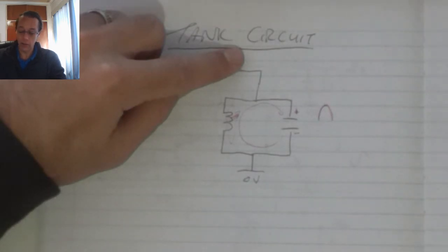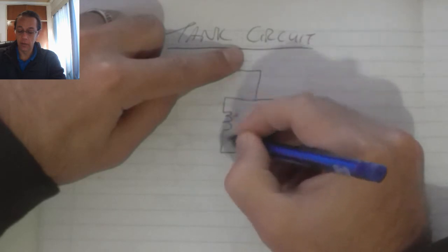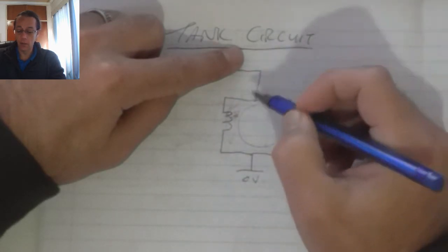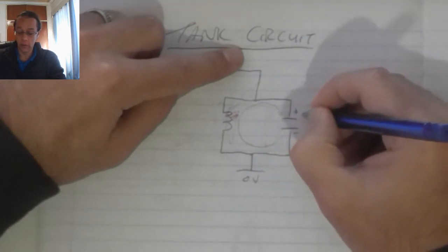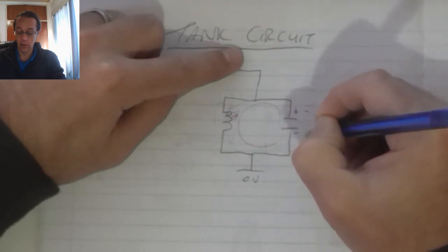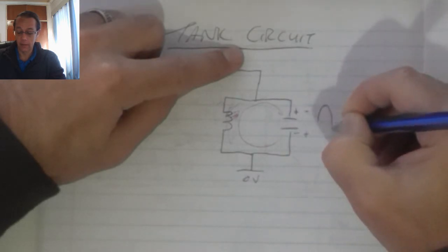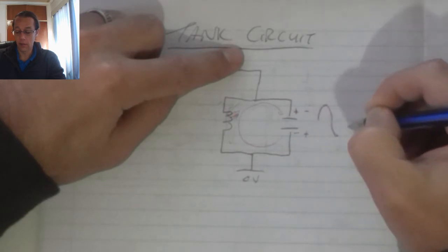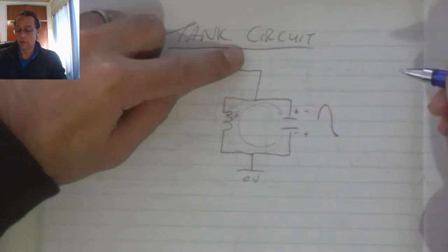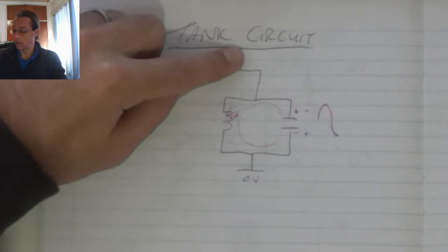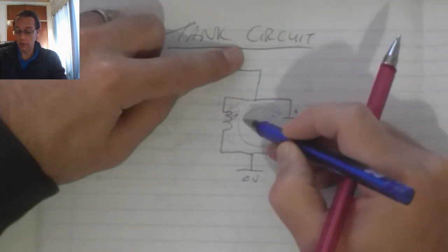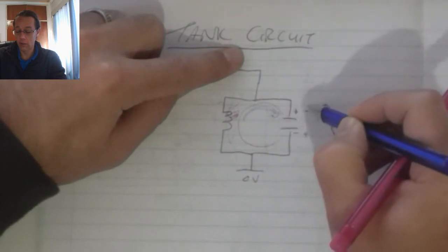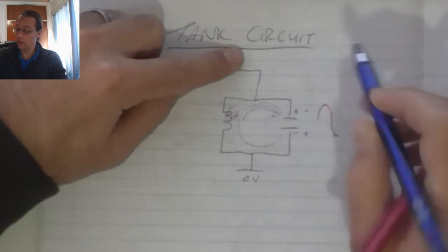Once the capacitor is completely discharged, this magnetic field on the inductor is going to collapse. Because it collapses, it induces a back EMF which charges this capacitor in the opposite direction, giving us a reverse voltage on the output. So this capacitor is now discharged, or the inductor's lost all its magnetic field, and as a result it has charged a reverse voltage on the capacitor over there.